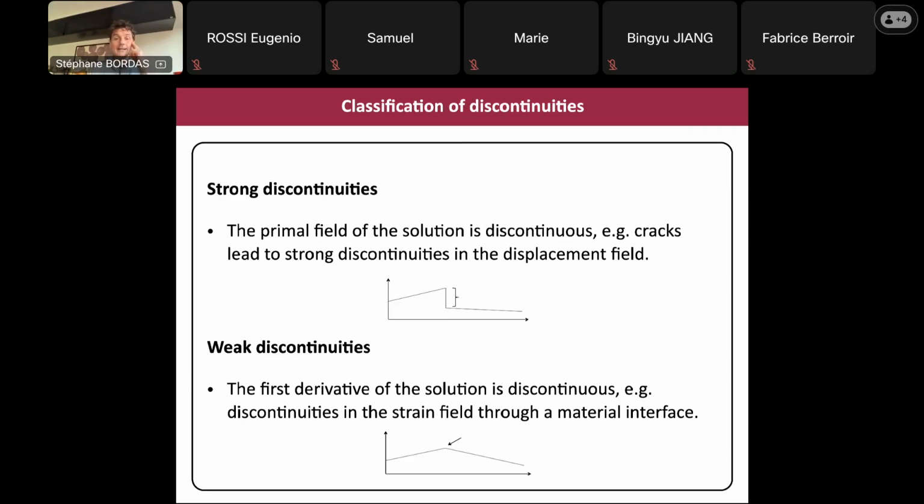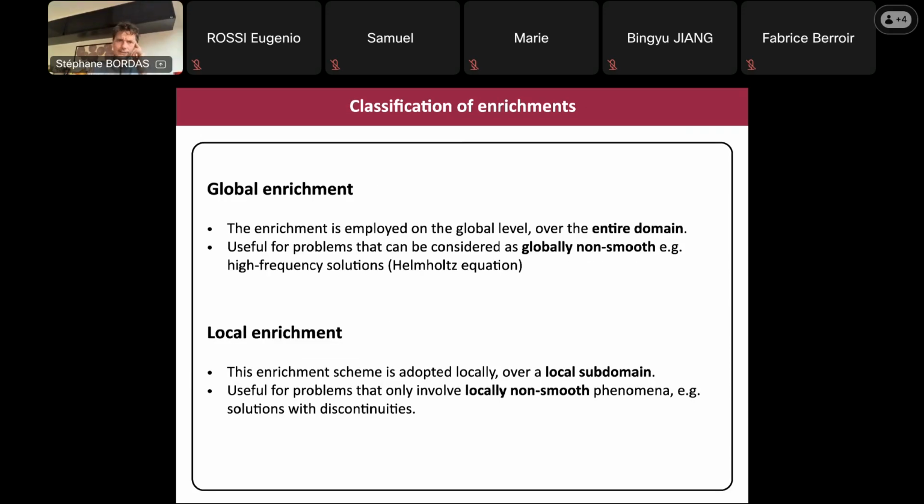You don't want that. Example, material interface between two domains. If you have two materials that don't have the same properties, you will have that case here, meaning that you will have a different level of strain, which is the gradient here. The slope will be different, but the same level of stress. Otherwise, there will be no continuity, at least for general interfaces. There exist interfaces which transfer stress in an imperfect way, but that is very technical, and this is not something we discuss here.